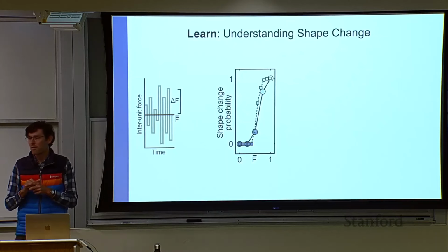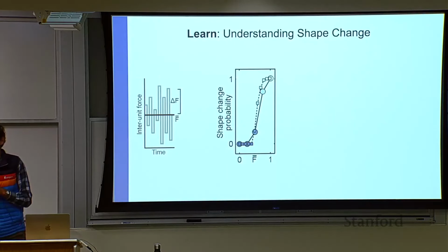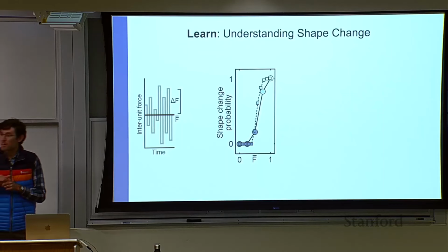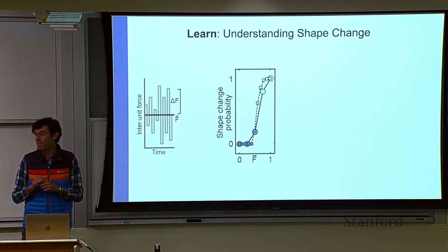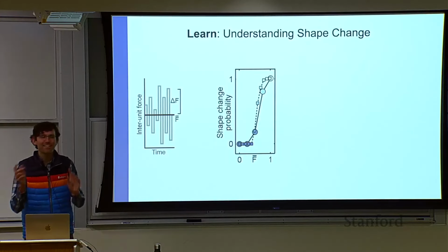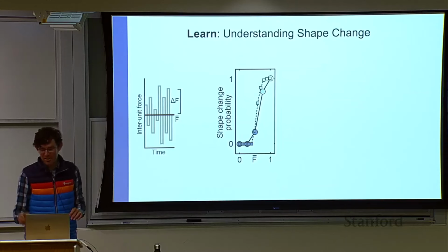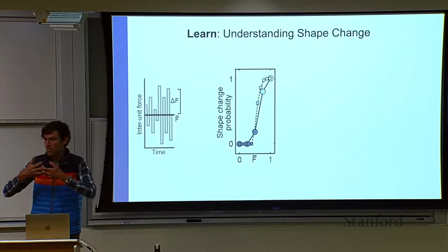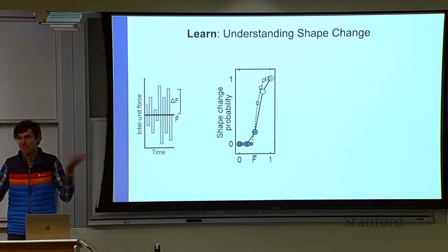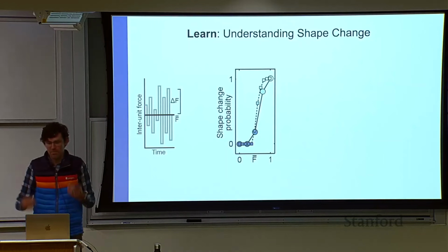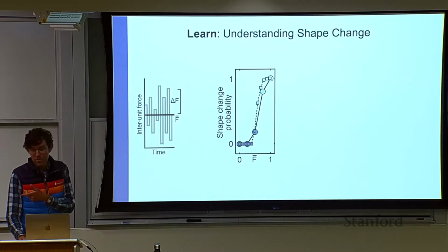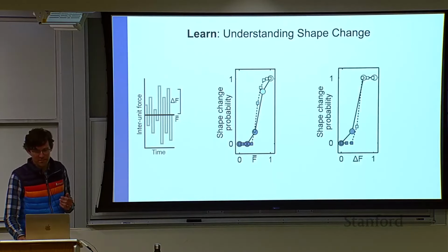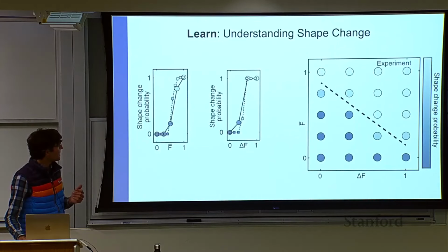A detailed question. The gears are easily profiled, so you're getting maybe tangents 25 degrees apart also. Yeah, which I think is key. There's a whole other study on gear shape. There are a lot of details we're not going to talk about today, but the gear shape is an interesting one because if you get them more like a flat tooth interaction, it doesn't work at all because they just lock up. And tooth size is important too, all these things. Great questions.